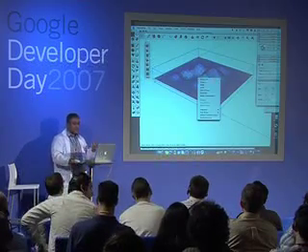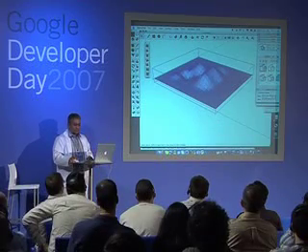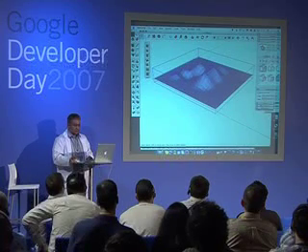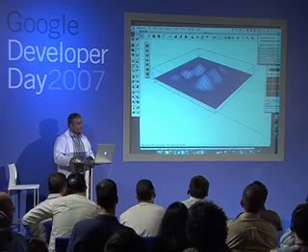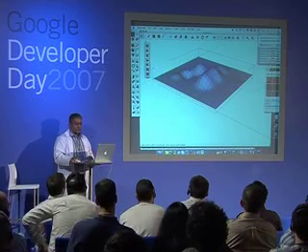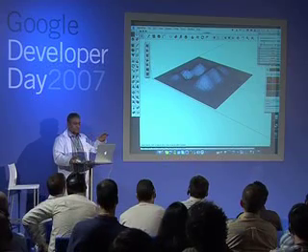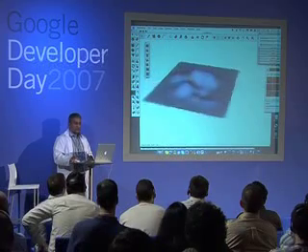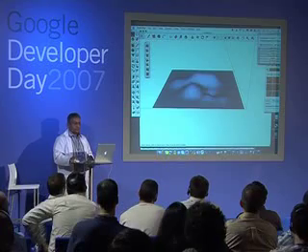You don't actually want those squares. I can actually select that and use my soften tool. Okay, the soften tool, where's my soften tool? Let's switch all of these off. There you go. My soften tool, what it does, as I move my slider, it will get rid of all the coplanar lines and make it much, much smoother for you. So everything remains in profile. So if I rotate, you see the edge appear.